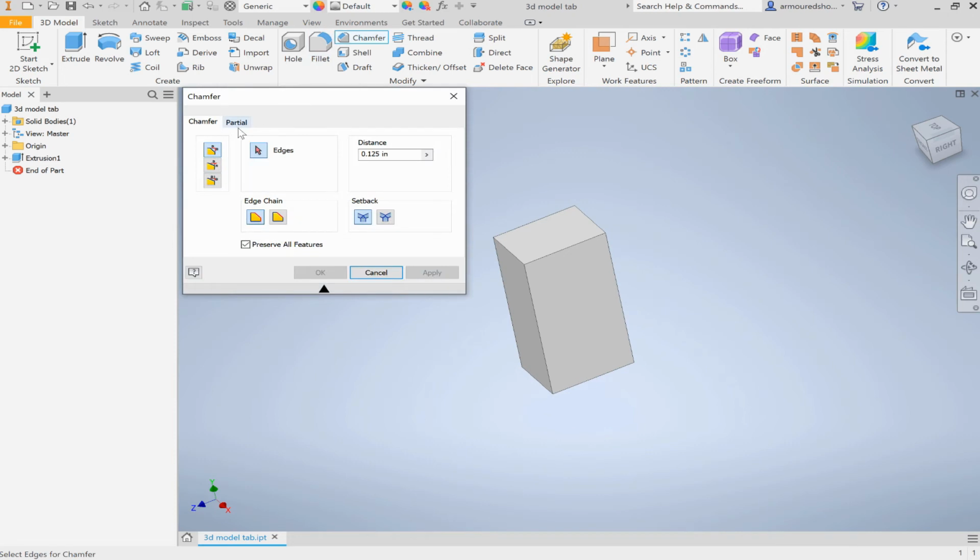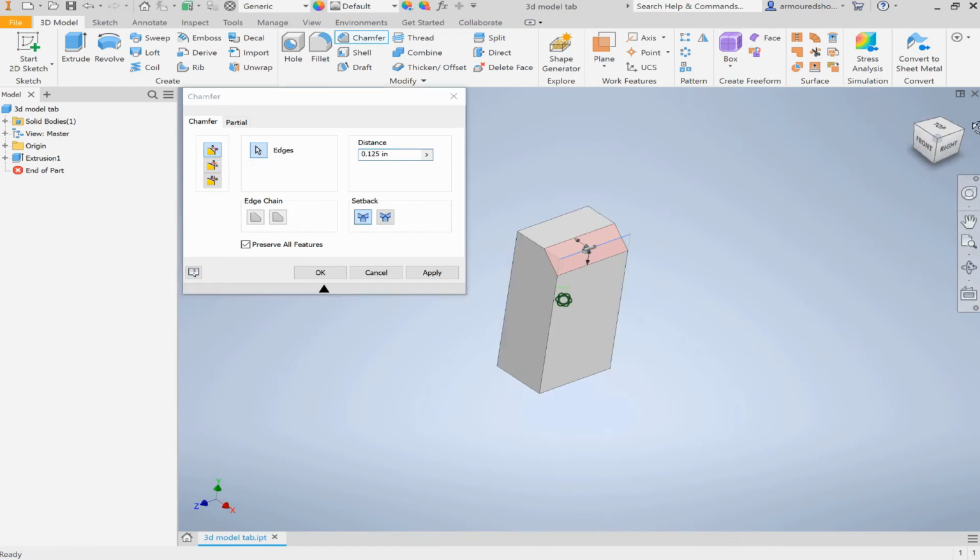And chamfer works very similarly. It cuts a bit off. You can also do other options, like you can see it's pretty clear. If there was a triangle, we're taking this triangle off. You can see we have distance and distance. This is the distance we're giving it, and it's taking distance and distance and just deleting that bit. We can also give it one distance and an angle, or we can give it two different distances, and it's pretty cool and very versatile.